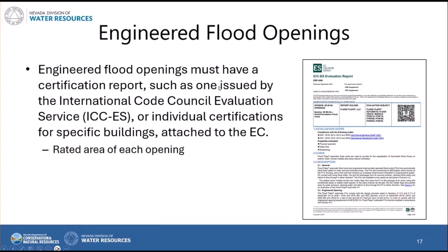As I mentioned, engineered flood openings typically come with an ICC-ES or International Code Council certification or evaluation report that describes the kind of flood opening it is, as well as its rated area. So let's say each of these engineered flood openings is rated to cover 220 square feet of enclosure. There's space on the form to enter the actual size of the openings and explain what they're certified to cover, and then do the multiplication. We have 4 engineered flood openings at 220 square feet each, and so those 4 openings will cover 880 square feet of enclosure. And the form in A8 or A9 will allow you to do that.